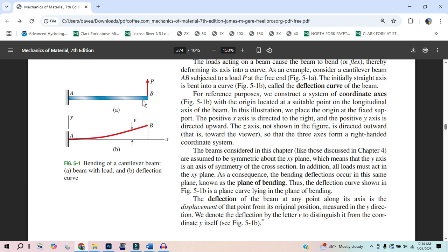It's the same thing as, hey, if I put a moment over here and I put a moment over here, two opposing moments, but we have to say that those are both causing a smiley face. You know what I mean? So the same aspect applies with shear, and I can kind of foreshadow why. If I have this little chunk, I think we got that visualized. Here I'm going to have that downward force, and then here an upward force. And let's take this chunk to be a little square, because they're going to do that on you with these shear forces and elements.